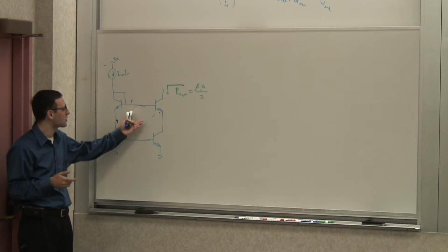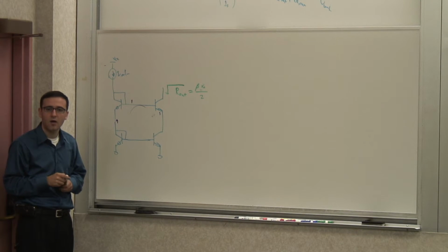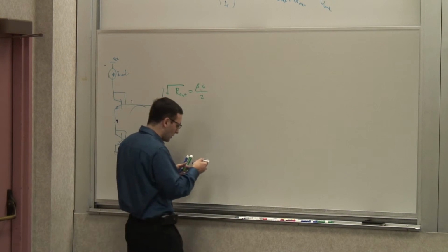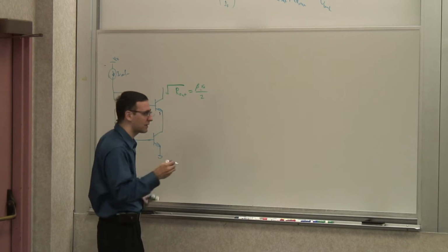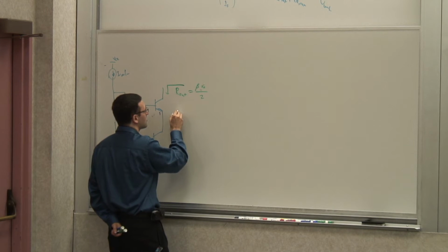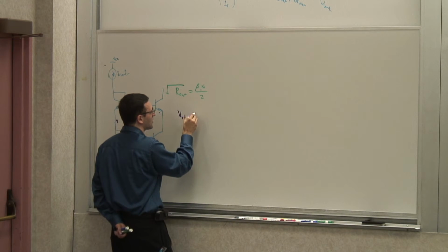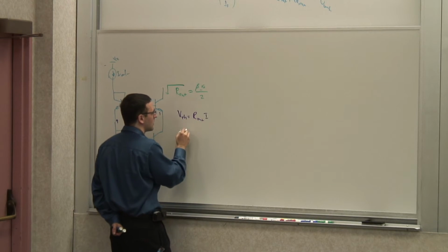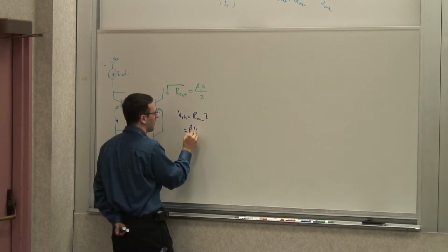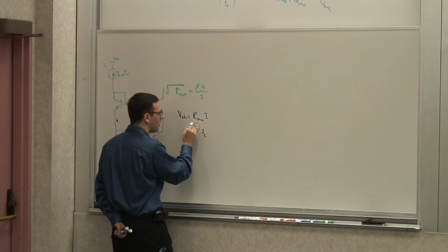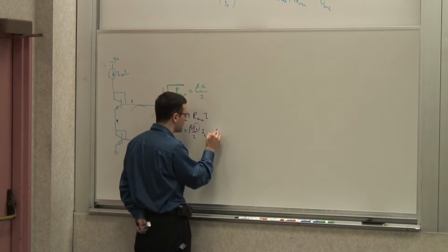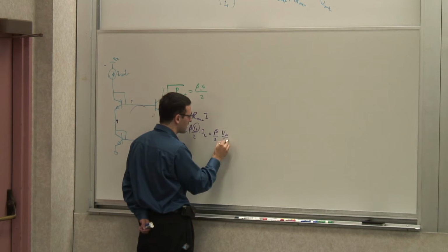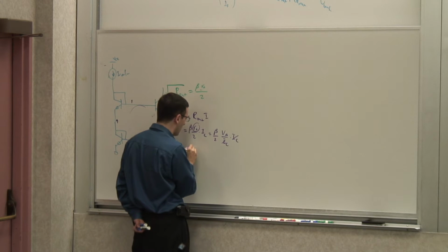And this is called a cascode current source. Now, let's look at the cascode current source. So we know its output resistance is high. So let's calculate its equivalent Thevenin voltage. You remember what the Thevenin voltage was, right? So the Thevenin voltage is the product of the RO and the current, which is basically the product of beta RO over 2 times the collector current. What is RO? VA over IC. So it's beta over 2, VA over IC times IC. So now you can see